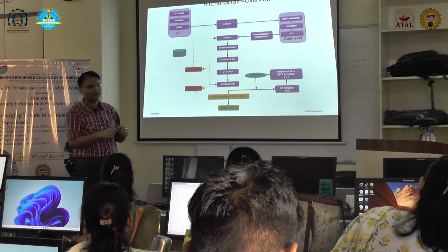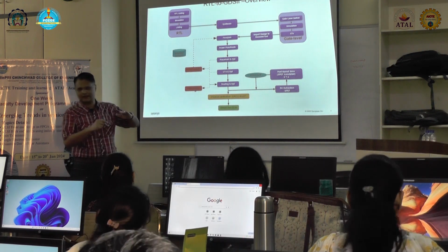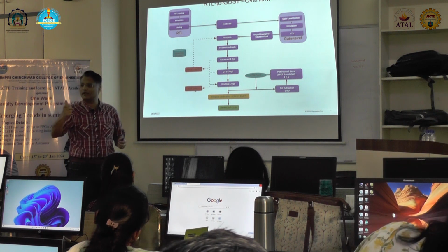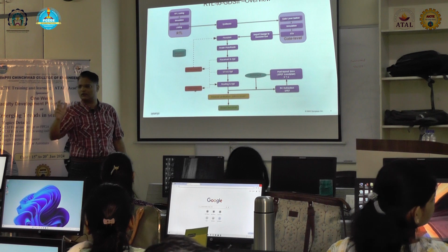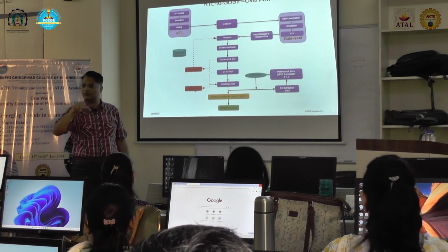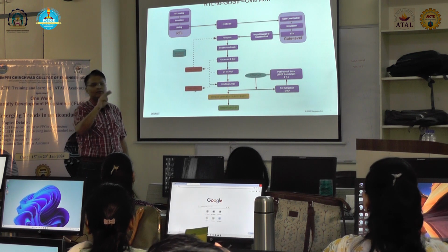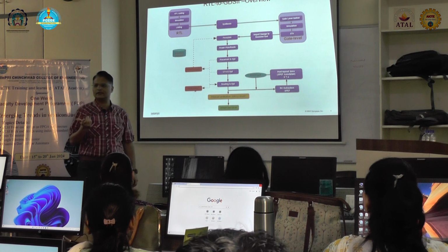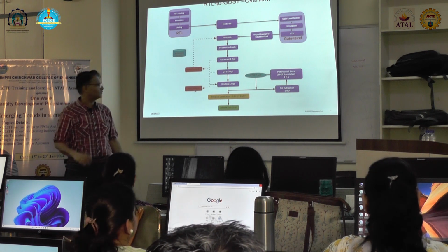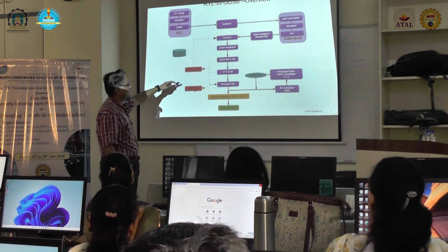And it might happen that it interferes with the signal and makes it also 1 for more than, let us say, so by definition we wanted alternate clock 0, alternate clock 1. But due to interference, what will happen? You might see that it is set for 3 clocks together and then it decelerates. So then the signal functionality has failed. So those kind of checks we will perform at the crosstalk.